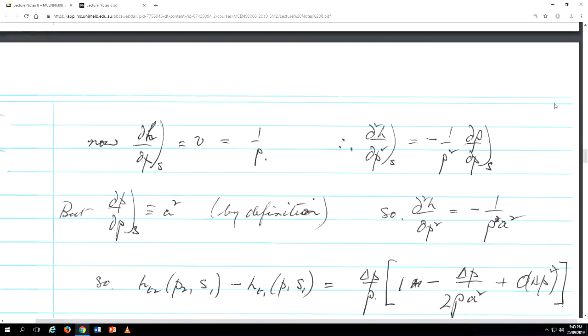It obviously has the units of a velocity squared, because of the pressure P in the Bernoulli equation, P over rho plus a half U squared. So dP/d rho will have the units of a velocity squared. And by definition, it's just going to be called A squared. And A is a function of temperature and so on. We're going to work that out later.